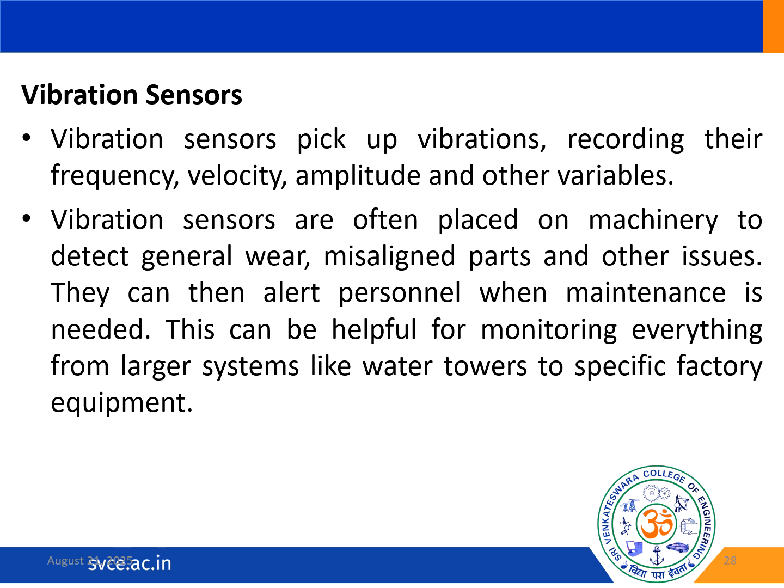As I told you, they measure frequency, velocity, and amplitude, and we use these sensors to assess the mechanical health of equipment. By continuously monitoring these parameters, they can detect early signs of malfunctioning, misalignment, or imbalance in machinery.